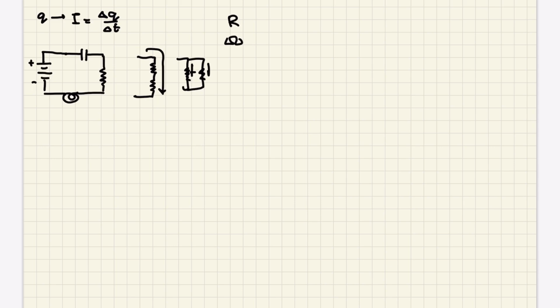Think of it like density. It's a property of the material rather than the object itself. And using this resistivity, also symbolized with a rho, just like density, we can multiply it by the length of that wire over the cross-sectional area of that wire, and that's going to be equal to the resistance of that wire. While wires generally do have some amount of resistance, it's usually negligible. And these resistors have a lot of resistance, and they're designed to be that way so they can have some current going through them. Why does resistance need to be there for current to go through?